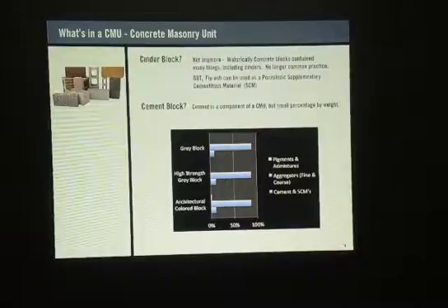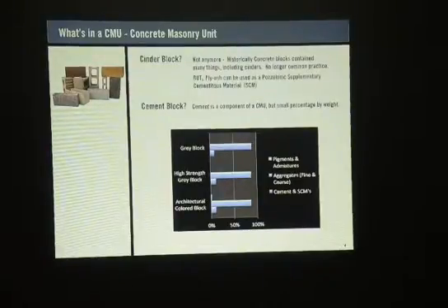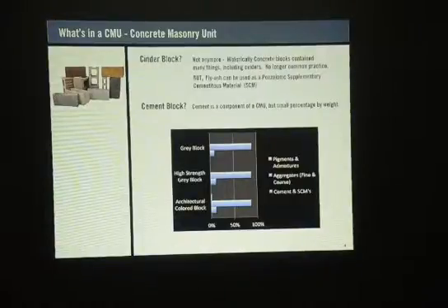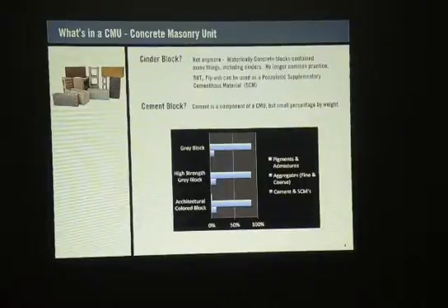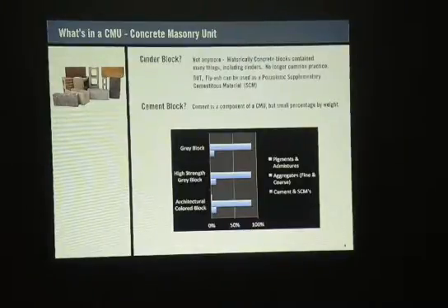Now, what does that do for your client, Mike? What's the benefit of going with block? That means less loading of equipment. So they may not have to have such a sophisticated heating and air conditioning ventilation system, but they can have maybe a lesser, less expensive, but still high energy efficient type of a block building. And that's important too when looking at these aspects. So this reduces the amount of grout, right? Yes, it does reduce the amount of grout. It's still fully grouted, but only where there's space available to grout.